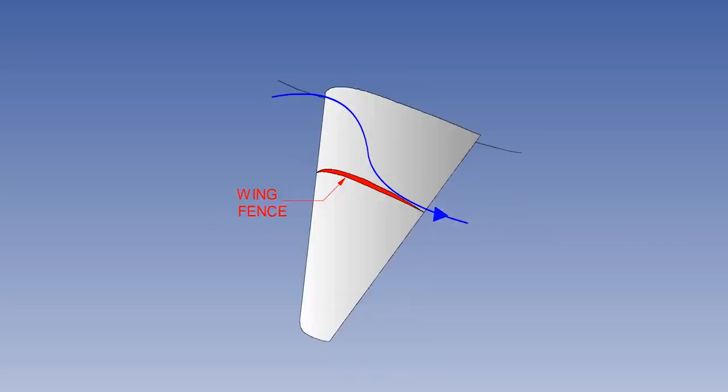The tendency of a swept-back wing to tip stall is due to the induced spanwise flow of the boundary layer from root to tip, and there are several design features that can be incorporated to redress this effect, to give more acceptable stall properties. Wing fences are thin, upright metal strips, which generally extend from leading to trailing edge and restrict the outward drift of the boundary layer.